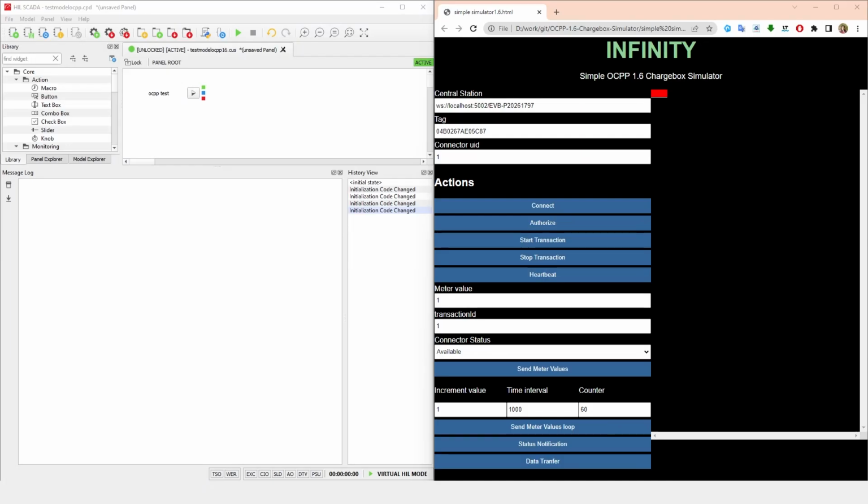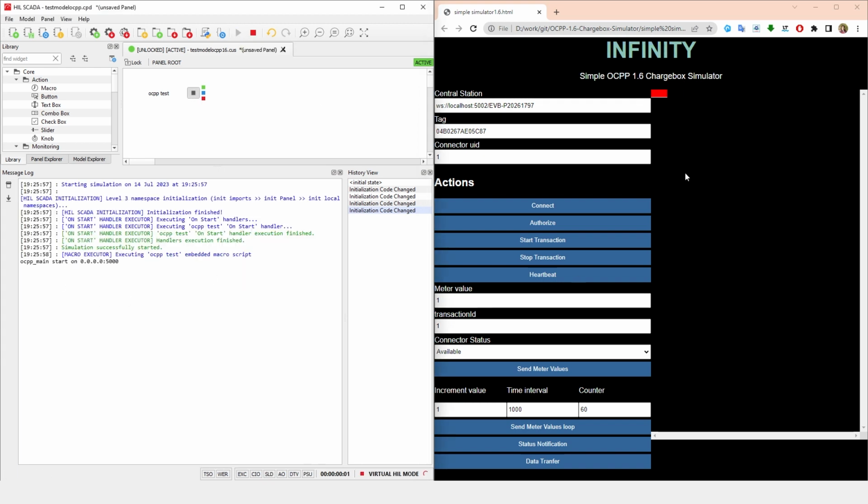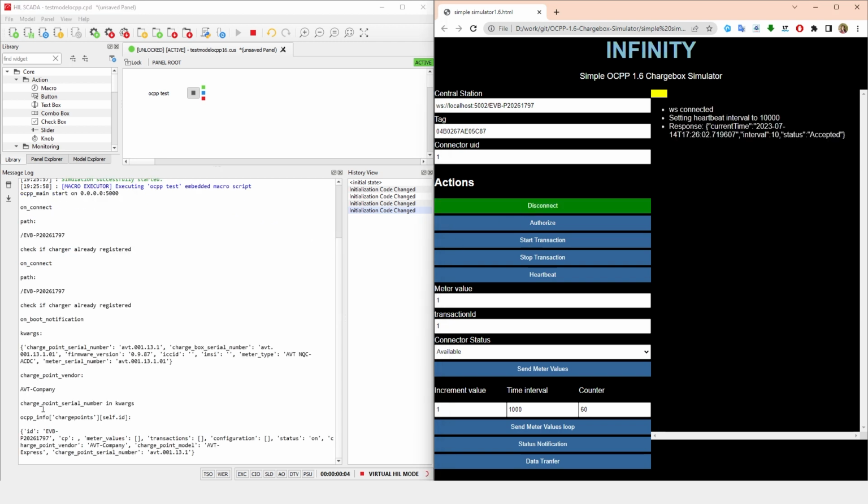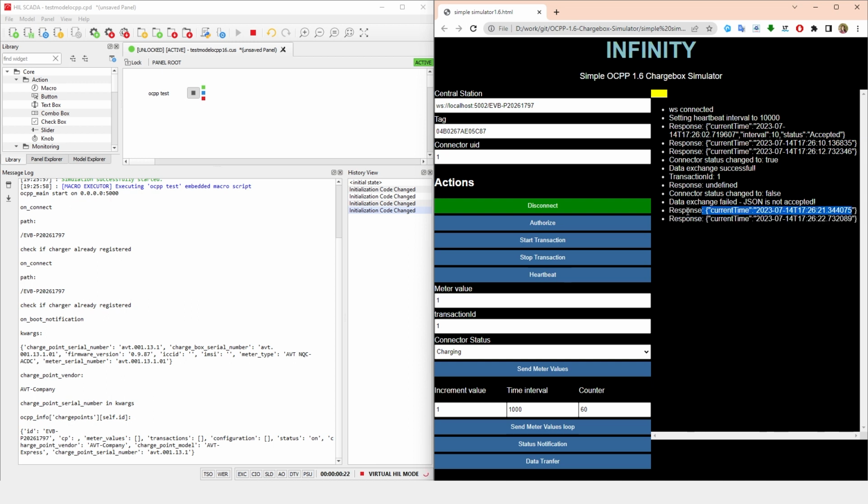Open Charge Point Protocol, often referred to as OCPP, establishes a standardized language for communication between electric vehicle charging stations and central management systems, or charging network operators. In this release, we've introduced a streamlined Python wrapper script designed to facilitate the use of the OCPP protocol within your platform. This Python-based script, which can be easily deployed within the appropriate SCADA interface, shows how to simulate a central system with OCPP server-side to control and test EV chargers that also run OCPP protocol.